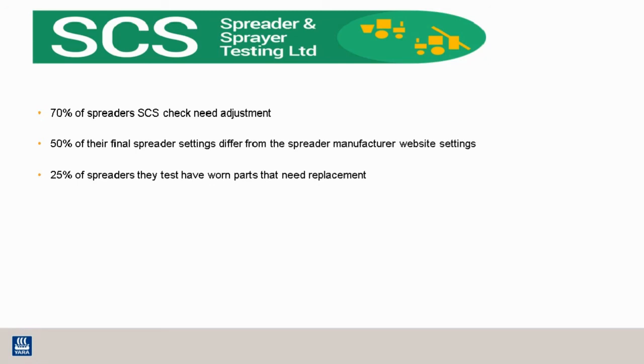And the vanes are the most common wearing part, although some manufacturers are now using hardened coatings, which are extending their working life. And also the agitation systems are common causes of spreading problems, and checking how fertilizer flows onto the disc is an important consideration.